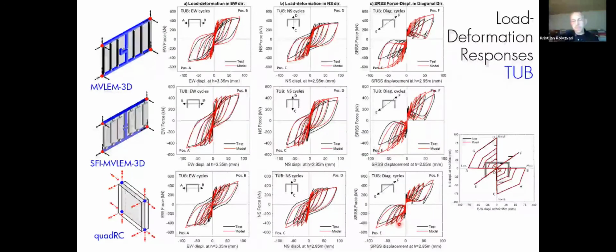And then what makes me think this, the only substantial difference between these finite element models and the macro models is the plane sections remain plane assumption. So that assumption is not really a good assumption when it comes to diagonal loading, which I will show you later with some strain responses actually. But just off the bat, looking at these results, when it comes to diagonal cycles, that assumption just doesn't predict strains very well. And when you use finite element, you can actually capture that shear lag effect and nonlinear strain distribution, which gives you better capacity predictions.